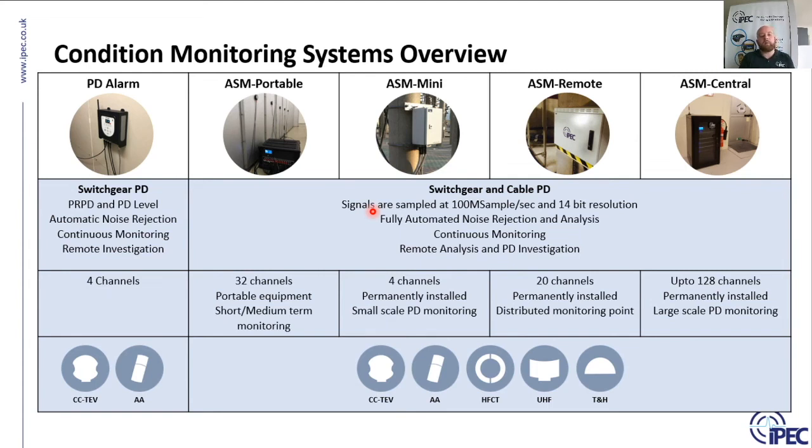And that is why we're able to fully automate the noise rejection and analysis. That's why, again, I said the IPEC system can operate completely standalone: we have quite advanced systems to differentiate PD from background noise. And I'll come on to how they work in a moment.